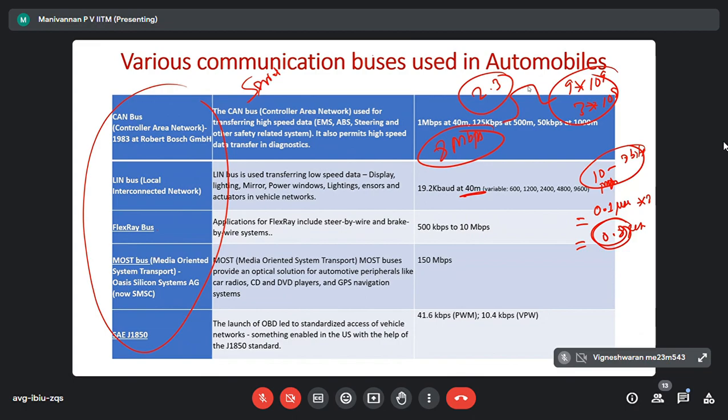If you talk about a big excavator, it will not move fast. A 1000 HP engine, the crankshaft will not speed up. What is a ship engine speed? Any idea? I think somebody is here from a ship, no? Jagan. Yeah, 100 RPM, 200 RPM, because with 80,000 HP, the crankshaft weight may be hundreds of tons.